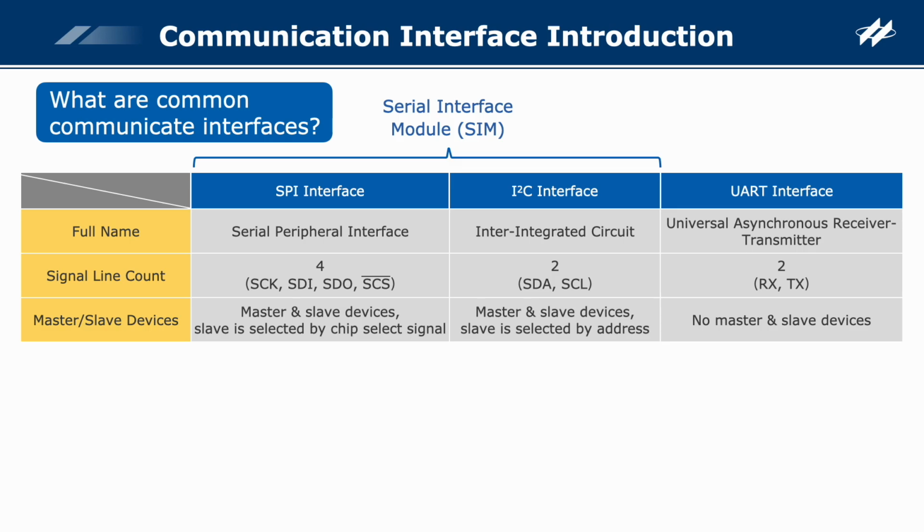The SPI communication is carried out in a master-slave mode, where the master controls the synchronous clock signal. The SPI communication allows a single master to communicate with different slave devices by controlling their chip select signal line. Similarly, the I2C communication is also carried out in a master-slave mode, where the clock line is controlled by the master, data transfer is controlled by the clock signals, and the master distinguishes between different slave devices by their address. However, the UART interface does not have a master-slave relationship.